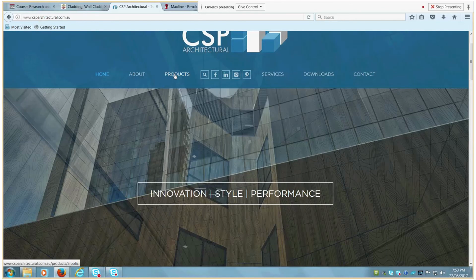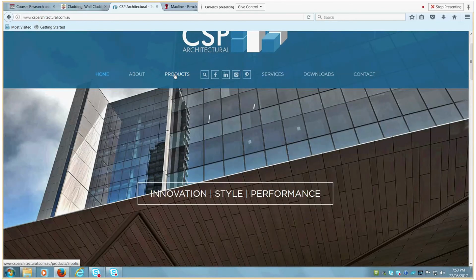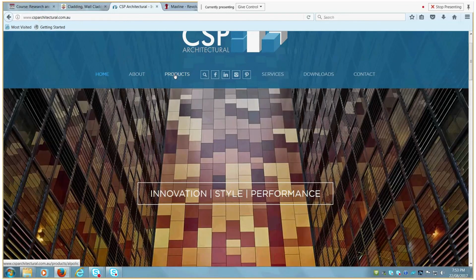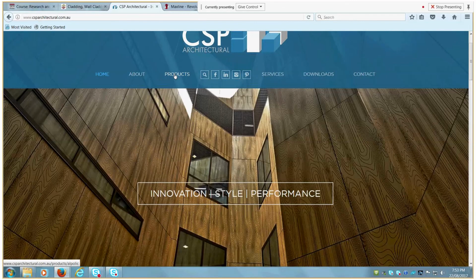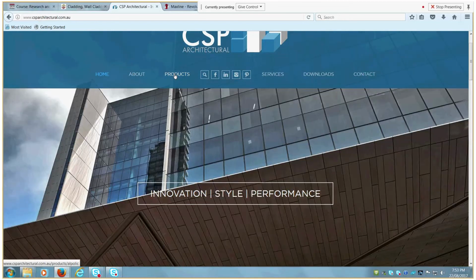So with bringing things from overseas, for some things there are compliance issues, of course, which you're well aware of. There's the Australian standard to fall back on, and whether those materials are being tested. A really hot topic at the moment is aluminium sandwich panels. I wouldn't use anything that's Chinese made or certified by some Chinese laboratory, because it wouldn't be compliant with the Australian code. They wouldn't pass Australian standards, which are actually pretty high compared to the rest of the world.